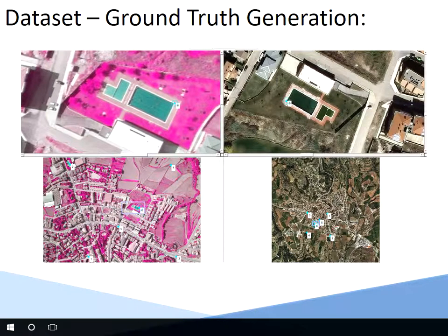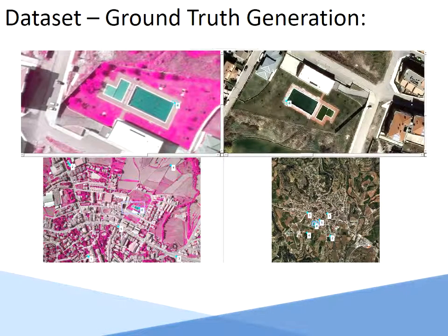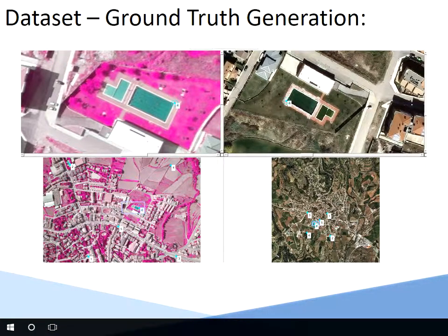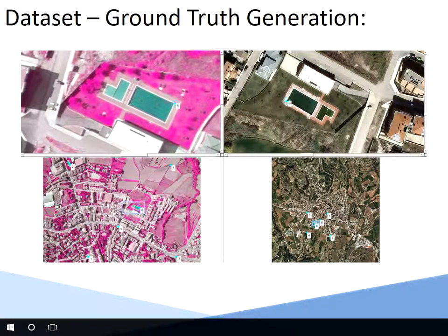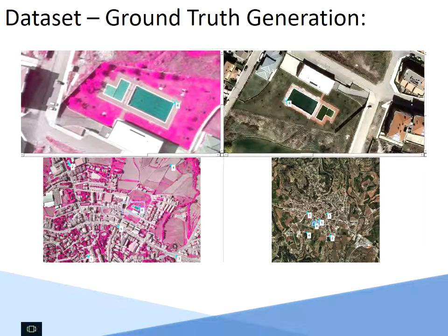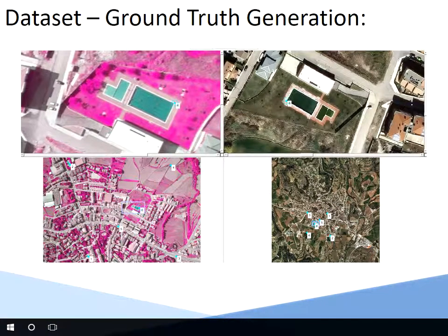So what we decided to do is to just add a bunch of control points added manually in order to reference these glue points that we will know are exactly the same positions in both the UAV imagery and the reference, and trying to find those points that we know won't be modified by the perspective.